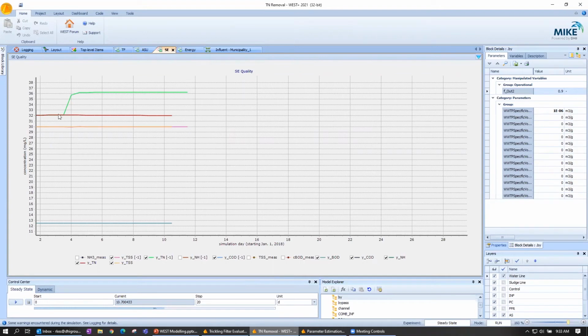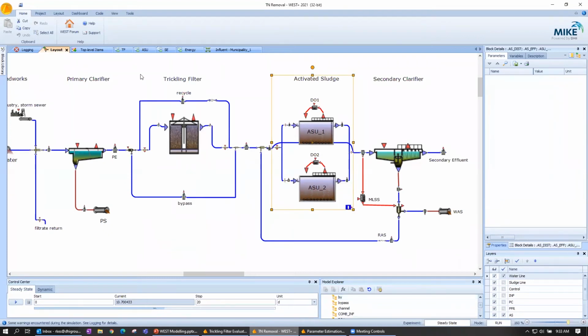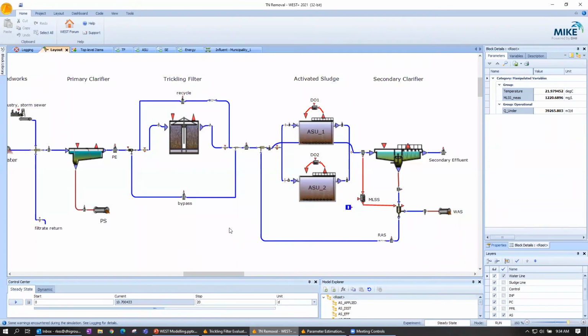So anyways, we see this change in total nitrogen, and that tells us pretty much only one thing. If we bypass the trickling filters and we can get 4 milligrams per liter less nitrate, that tells us that we're carbon limited in these tanks, and that taking out carbon in the trickling filter is maybe not that useful of an exercise anymore. That's not to say currently the trickling filters aren't needed, because that's not how we operate the plant.